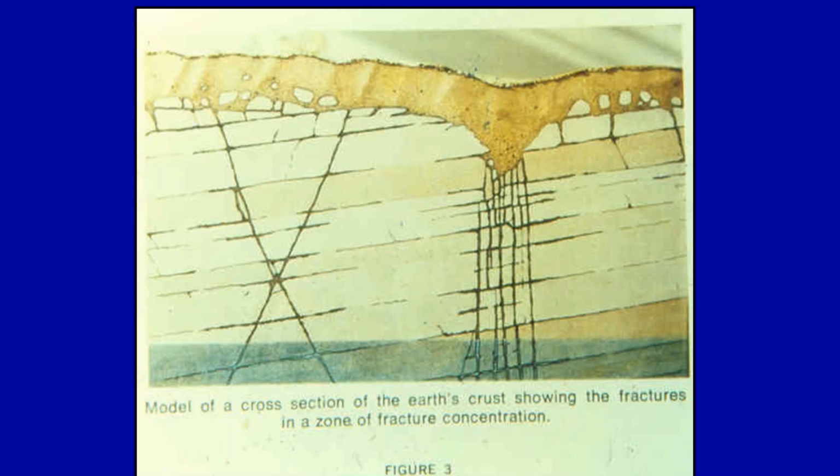But this may be a zone where groundwater is and surface water is draining into the fracture matrix, and the material growing here is going to be stunted more than what is on either side. Well, using aerial photography, you can do fracture trace or lineament mapping and try to identify these features. And when they are identified, you look for an area where multiple fractures converge at a single location.